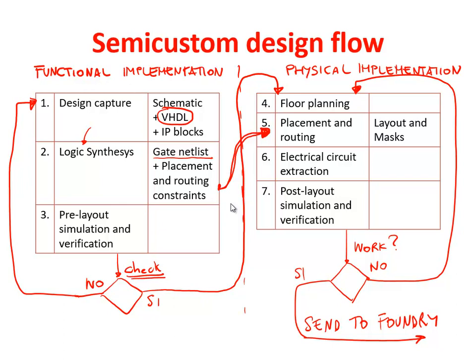And from a physical point of view, this depends a lot on the distance between one logic block and the other logic block to which the signal needs to go. For example, I can assume a certain delay in the signal from one logic block to the other, and this delay that I have assumed of course puts a constraint on the distance between the two blocks, because the more distant the two blocks, the larger delay I probably need to have.